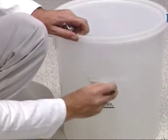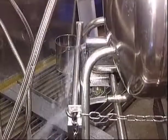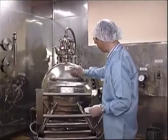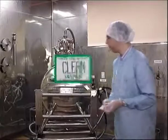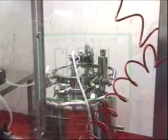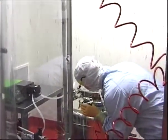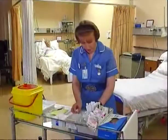These GMP rules have a specific purpose. They're designed to stop the tragedies that could and have happened when, say, the status label "cleaned" is put on a container that has not been cleaned. It goes unnoticed and so contaminates the next batch of a different product, and yes, you've got that one as well, more trouble.